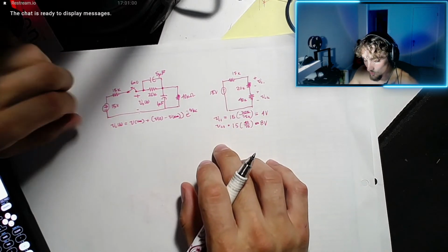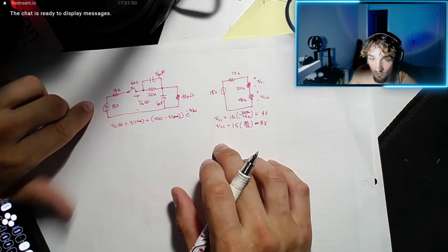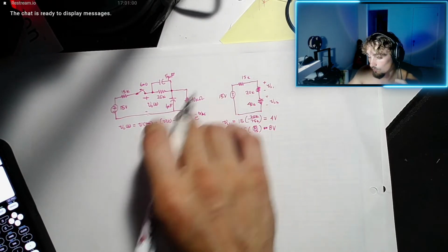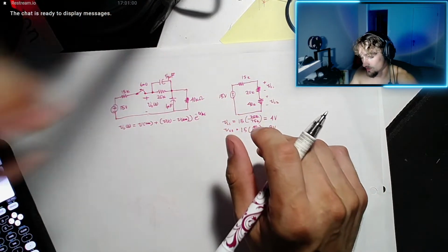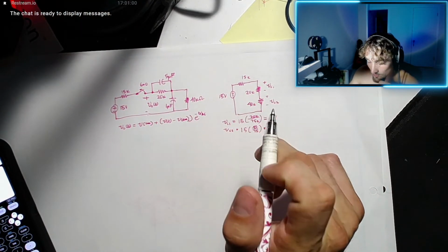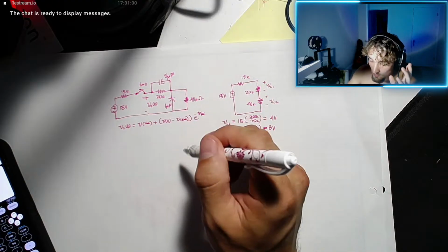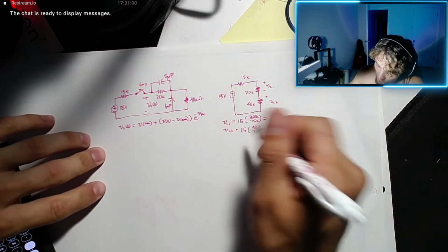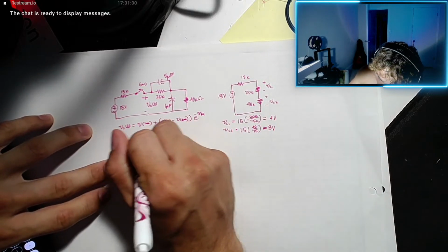After T equals open, we're separated from the 15 volt supply, and we're just going to be left with some voltage across these capacitors, which will discharge into the rest of the circuit. So it's going to be open there. We want to know V naught, the voltage across there. So our new circuit's going to look like this.